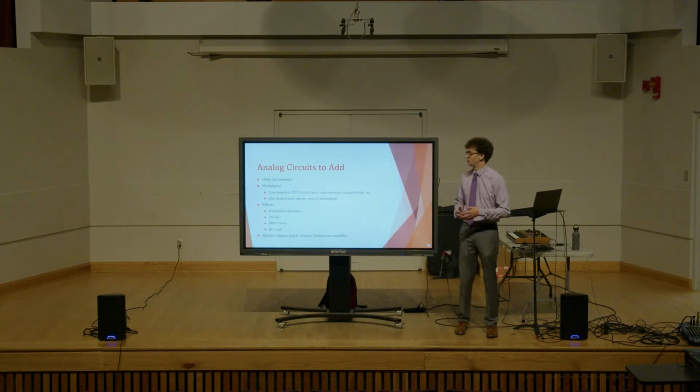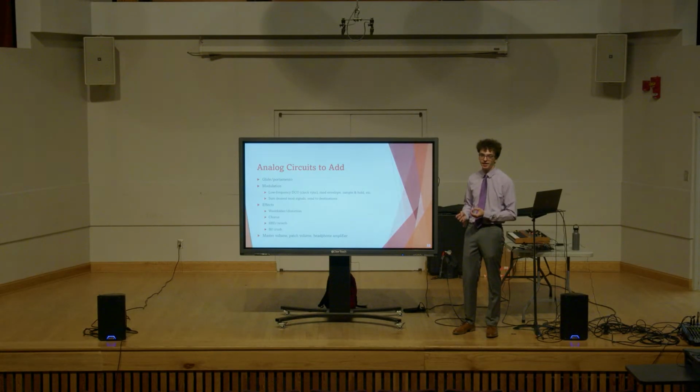And so what do I still have to do from the analog side? What I haven't implemented yet that is really important to me is a glide or portamento feature, which allows you to, instead of instantaneously switching between two notes when you press two notes, sort of slide between them. As you turn up the glide or portamento, it takes longer to get between each note, which is a really neat sound, and I think is part, to me, of the identity of the monosynth, and even just synthesizers in general. So that's something that I'll be implementing soon, and that can be something as simple as an RC circuit